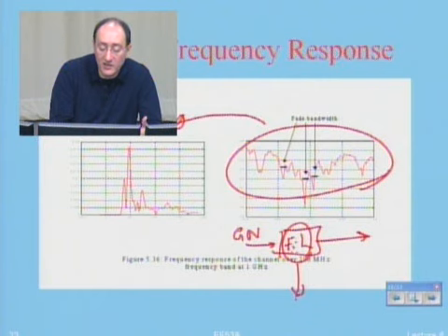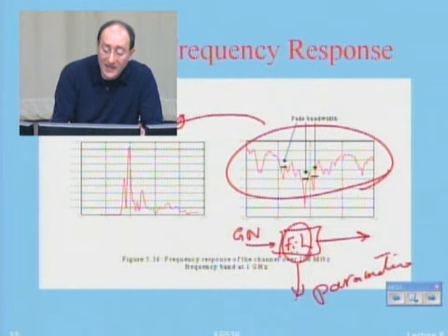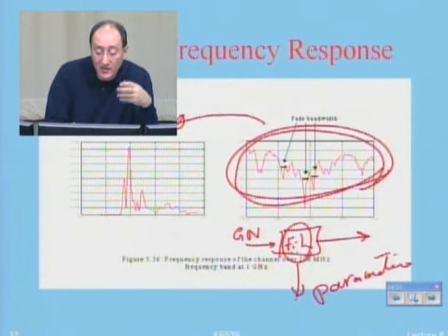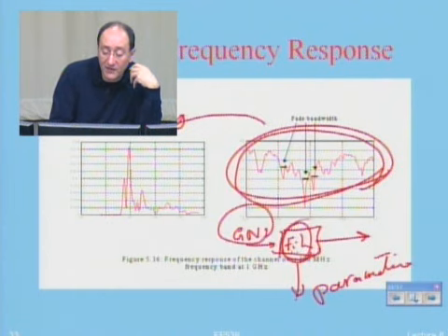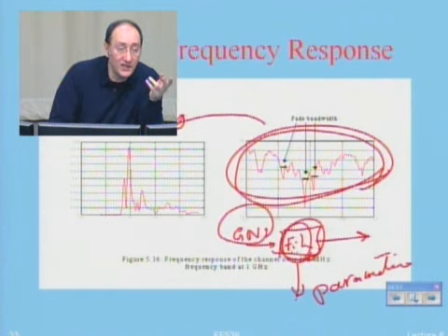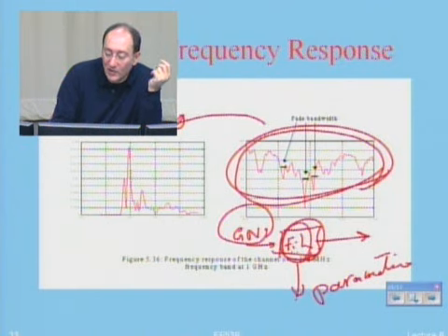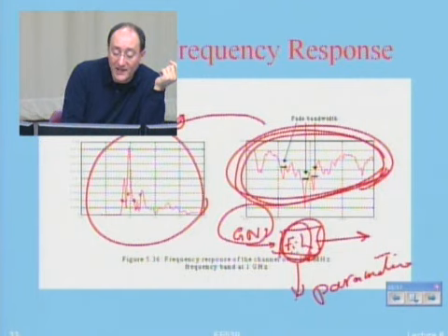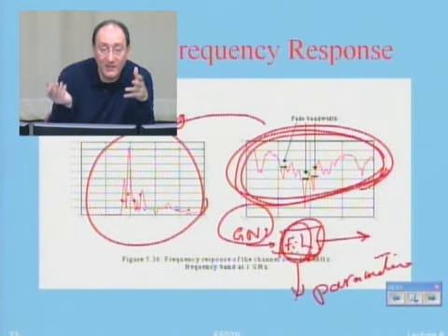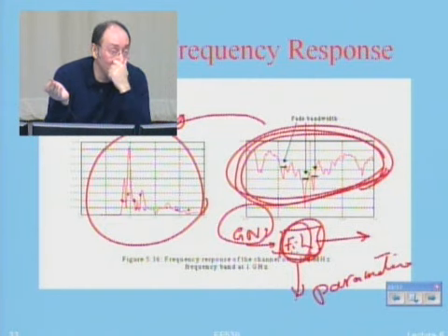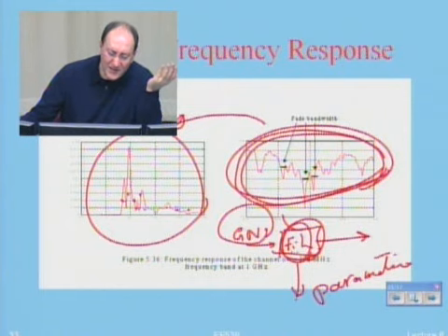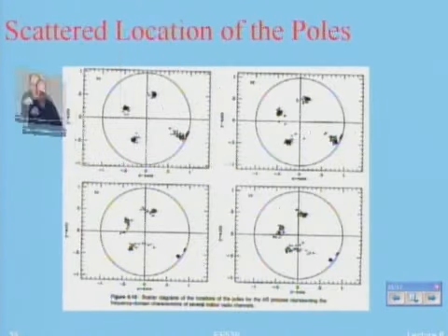This is called, in spectral estimation, parametric spectral estimation. It means that rather than, I want to model this, for example, in frequency domain, I model this with Gaussian noise running through a filter, and the filter has 2 poles only. So I have 2 parameters to model the entire thing. If I want to model in time domain, I have a bunch of paths, a number of paths, many parameters that I have to model. Okay? But in here I have very limited models. This is one model.